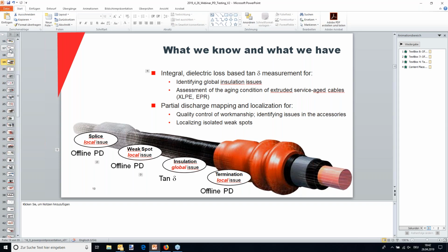So from our experience, since we're not direct competitors, it has some value to it. It is obviously not the perfect tool. I mean, the dielectric strength is another thing. It comes back over time. The compounds change every so often. They have these cryptic codes for naming these fluids, and it has some value. For some cable, it's not really applicable. Let's say, for instance, for bare concentric, you typically would not do that, and also not for unjacketed cable.